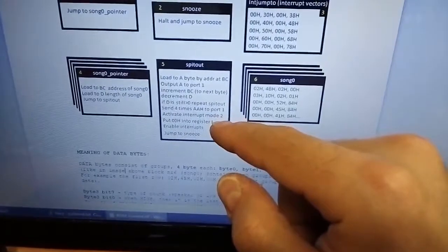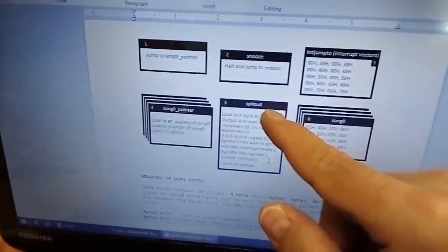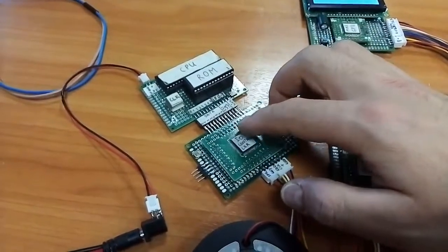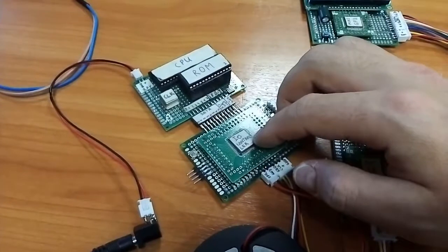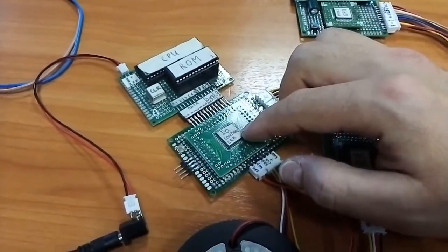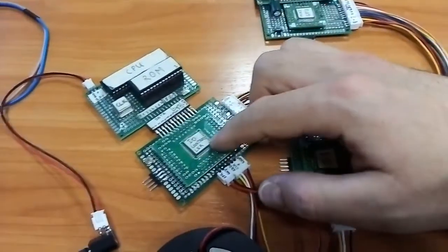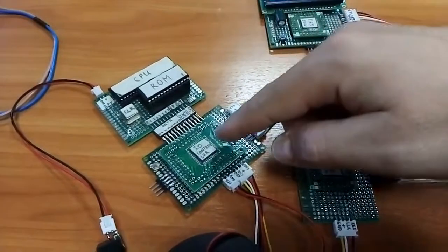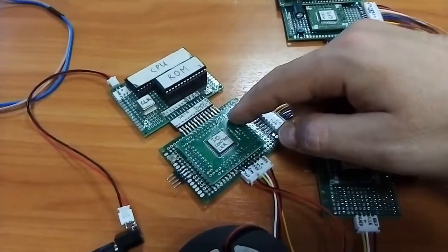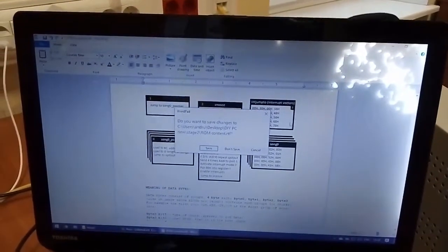But next, what does the CPU do? It snoozes, it sleeps. And what goes next? Next the controller wakes up when it receives 4 bytes of AA as a marker of end of transmission from the CPU. Then it stops listening to the CPU. All the time it listens to the keyboard, but the CPU listens to interrupts. The controller, as it has collected all the bytes into its memory, now starts to read and analyze them byte by byte.